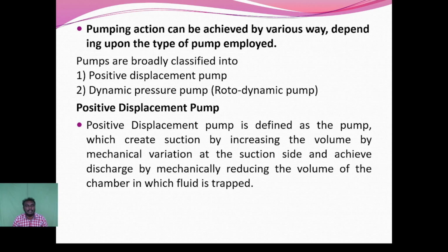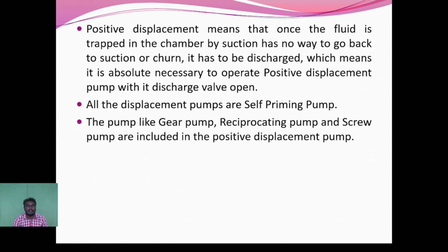The positive displacement pump is defined as the pump which creates suction by increasing the volume by mechanical action at the suction side and achieves the discharge by mechanically reducing the volume of the chamber in which the fluid is trapped.